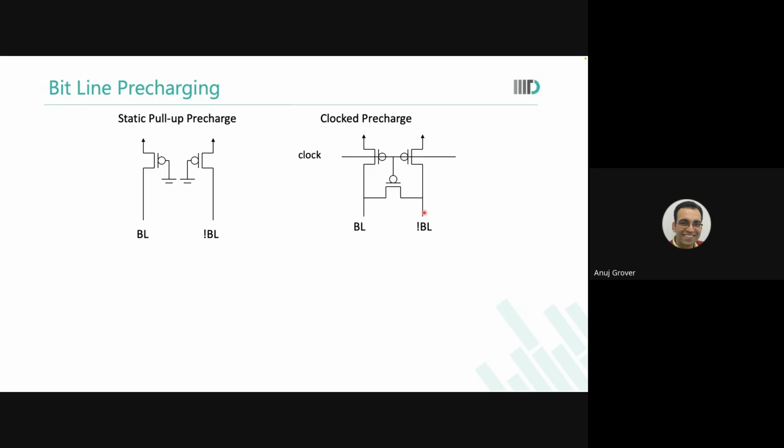Do you remember? We said clock goes high, internal clock gets generated, wordline gets generated, and somewhere we also said precharge goes off, so that when wordline gets generated, I'm able to create a differential on the bit lines, whether it is for read or for write. So during the read or write cycle, my precharge is anyways off. I'm not bothered about this equalizer being there or not being there. What I'm talking about now in terms of secondary benefit is when I turn the precharge on again, so that my memory gets ready, reset to accept the next cycle.